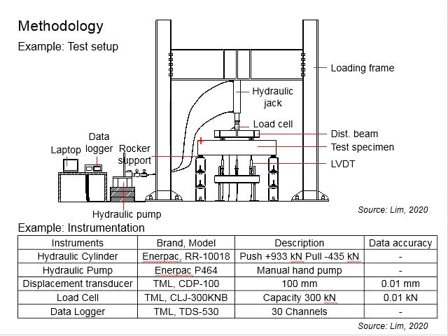You want to study the behavior of a reinforced concrete beam. There will be measurements, which are going to be a load cell, and there are 3 displacement transducers to measure the displacement. The load cell here is used to measure the loads acting onto the member, which is later divided into 2 loads. We assume that both vertical loads here will be equal. Now the question is, is it really equal?